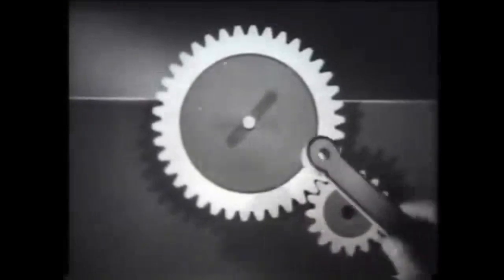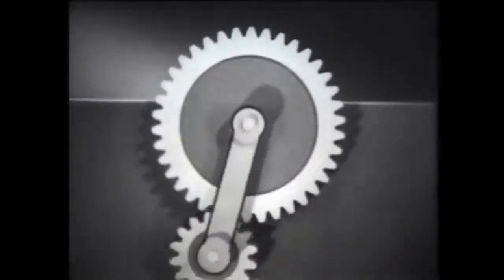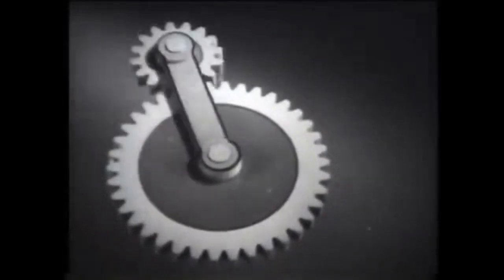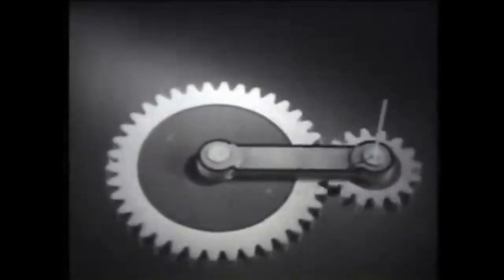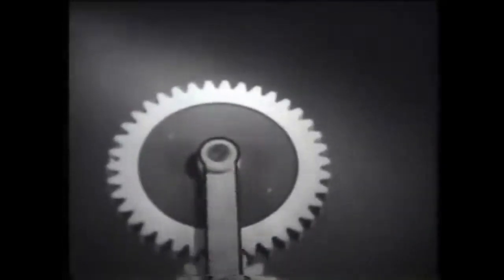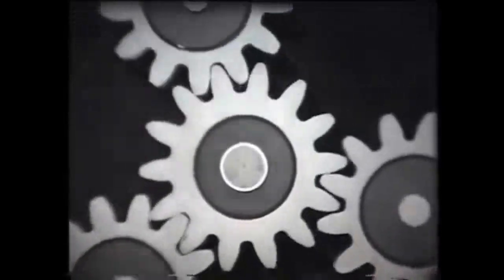The most progressive gears include planetary gear mechanisms. They consist of the following elements: the central sun wheel, satellites and a carrier. In such mechanisms there are movable wheel axles. The number of satellites depends on the purpose of the mechanism. These wheels can have teeth of both external and internal engagement.